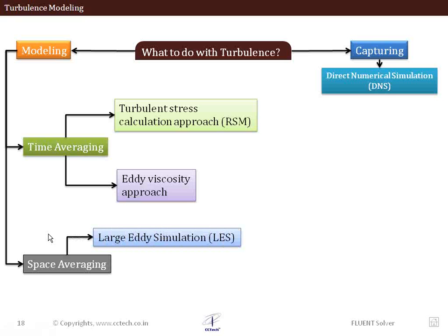The other approach, space averaging, helps us average out the smallest eddies of our problem, but the larger eddies can still be resolved. So you are doing some kind of direct numerical simulation of the larger eddies, while the smaller eddies are modeled. Therefore it's called the large eddy simulation. So this is the space averaging approach.